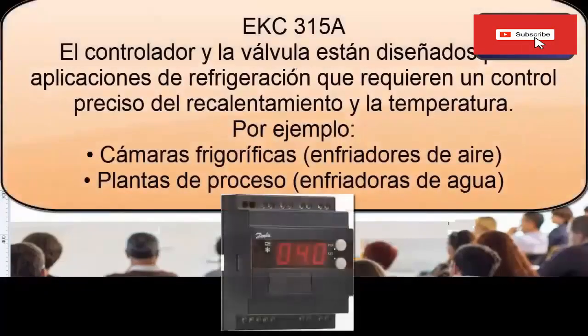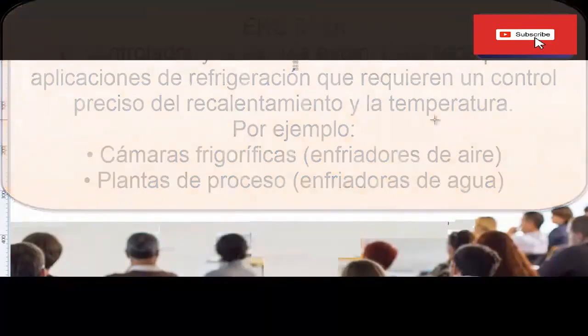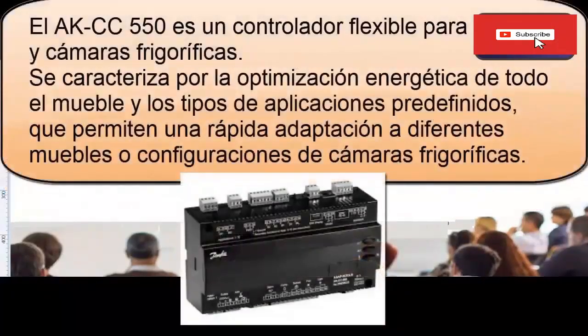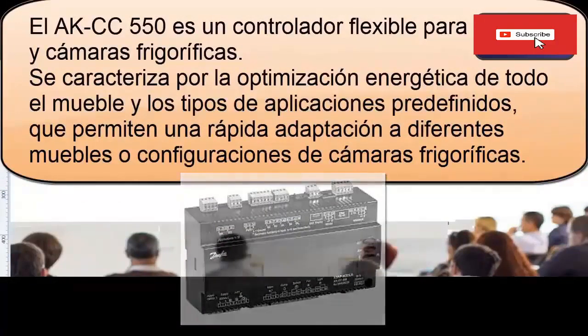I. Defrost stop by time. J. Defrost delay after emptying. K. Fan control when disconnecting the compressor. L. Evaporator temperature at which the fan stops. M. Selection of the compressor deactivation delay when opening the damper.